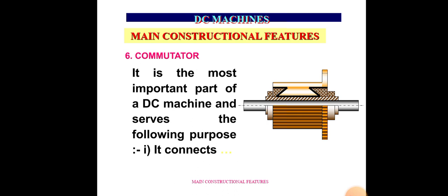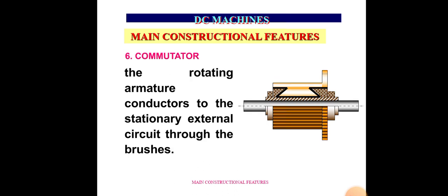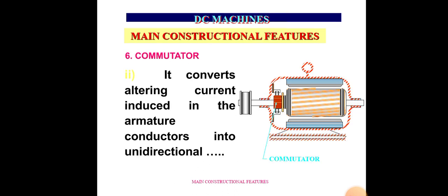The segments are held together by clamping flanges that pull the segments inward. The flanges are drawn together by bolts and cap screws. The flanges are further insulated from the segments by two rings of mica.